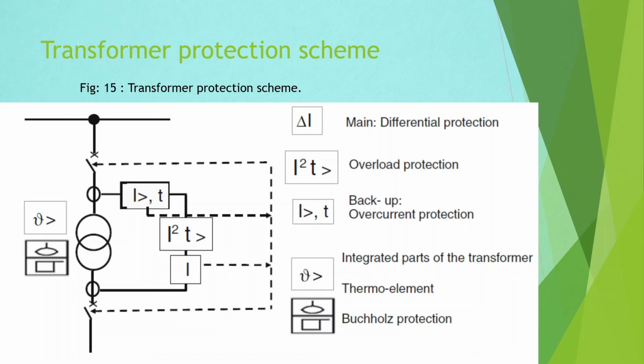segment. The typical transformer protection scheme is presented here in this figure. In general, the transformer differential protection principle is identical with the line differential protection. The differences consist of the following: adaptation of the measured current in accordance with the transformer ratio, direct measurement of the different currents in one IED, no need for blocking functions in accordance with the inrush current.